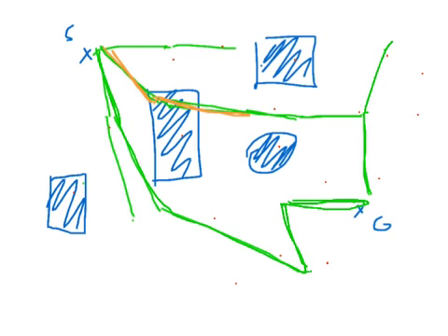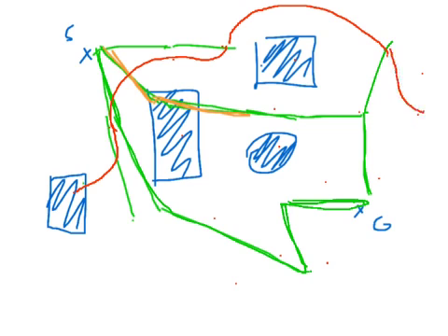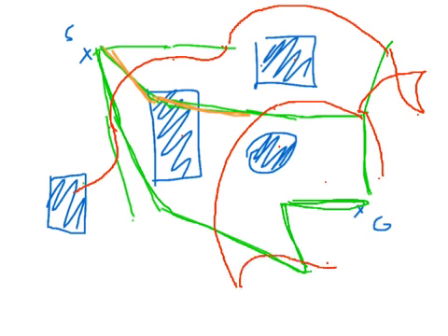Let's say we have a car-like robot. This car could only make connections like this, for example. So you see, every time I add a possible path, it is following a kinematic constraint that a car might have. So now I can create a graph that is collision free and actually feasible when I drive it with car-like kinematics. So these are some of many possible ways of connecting these trees.